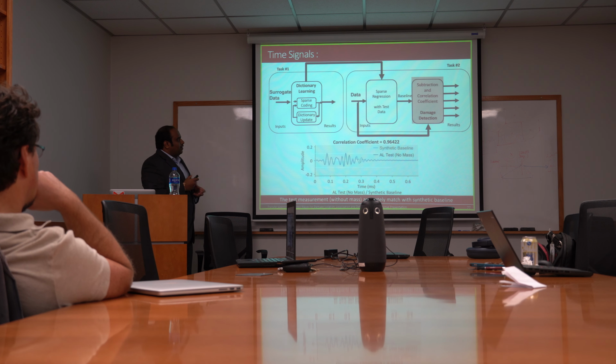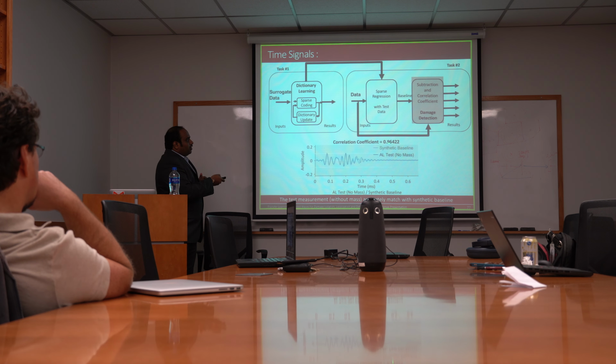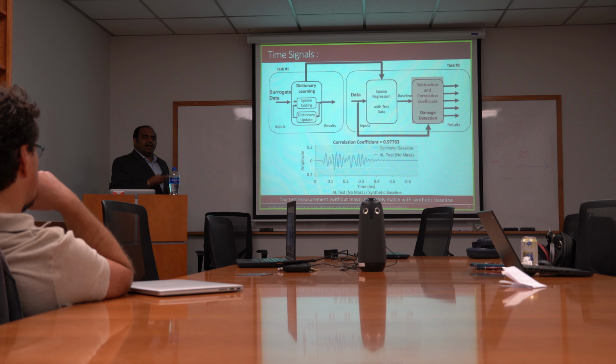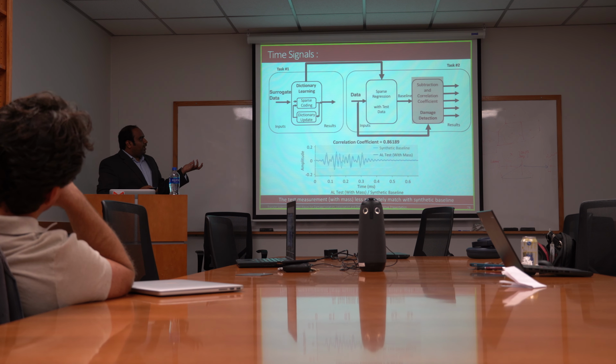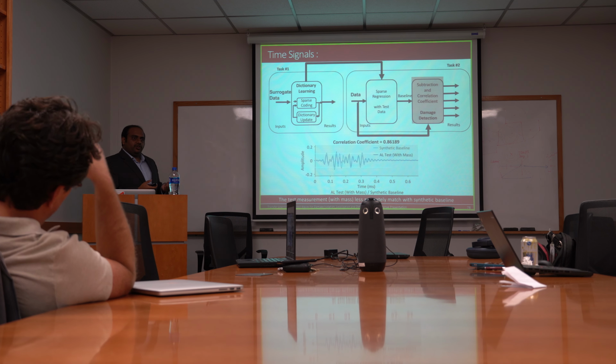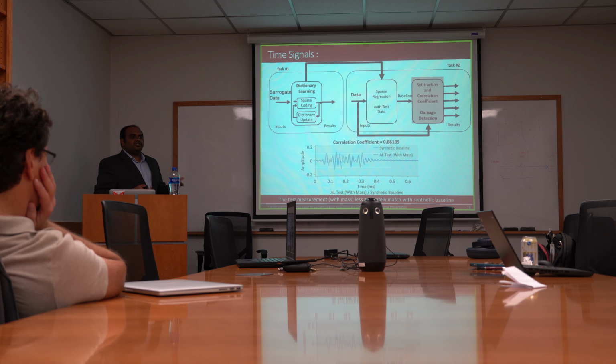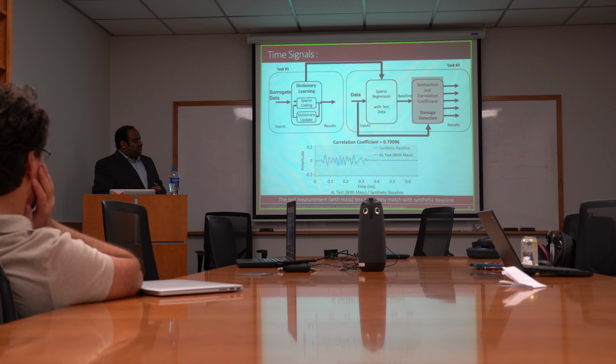The correlation is bad. Now, if I use my synthetic baseline generated from dictionary learning, you can see the correlation increases to 0.95, very high, 95%, when there is no mass on the aluminum plate. When there is a mass, the correlation drops from the high 95s to low 80s and 70s. So, can I use the difference of these correlation coefficients as a metric to classify a structure with or without damage, or to detect the presence of a damage on the structure?